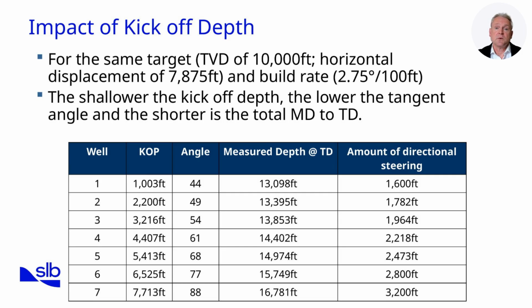As an engineer, one must consider not only the geometry, but also operational capability. Rig horsepower, mud pumps, and drill string design may all be limiting factors. Additionally, shallow kick-off points allow more flexibility in managing azimuthal corrections early, reducing course corrections later in the well.